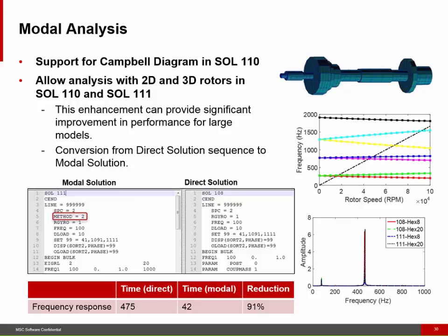So with this release, MSC Nastran 2017, it's possible to perform modal complex eigenvalues and modal frequency response for rotors with axisymmetric and 3D elements. Also, we added the option to generate Campbell diagrams in solution 110, which wasn't possible before.